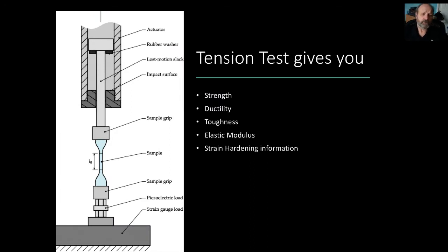So a lot of what we do in mechanical engineering is based around tension testing. Okay, tension testing is actually pulling on a material and seeing what happens. So let me get my little pen out. This is a tension tester on the left side. And what we do is we clamp using the grip a sample, right?